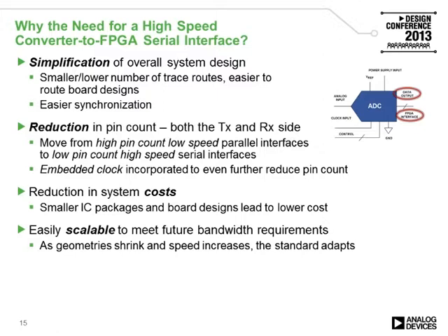So, what are the benefits? It's simplification of the overall system design. A lower number of trace routes allows easier routing of board designs. Synchronization also becomes easier. It's a reduction in pin count on both the transmitter and the receiver side. Move from high pin count, low speed parallel interfaces to low pin count, high speed serial interfaces. Embedded clock and framing even further reduce the total pin count.